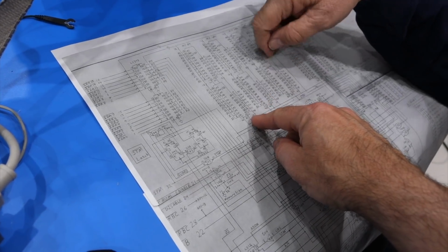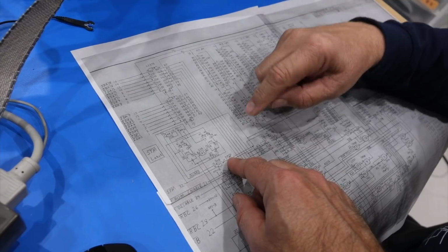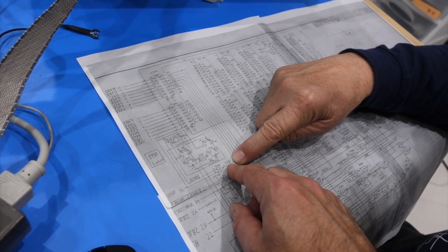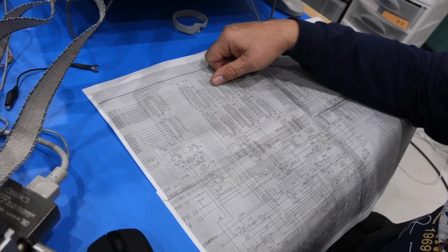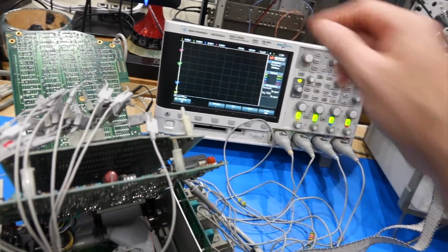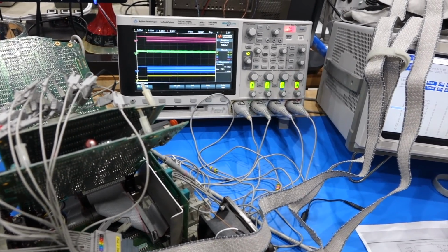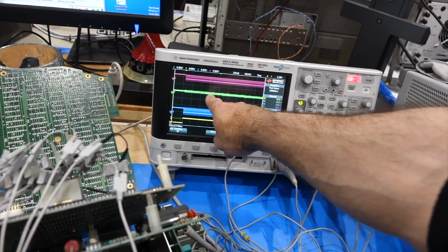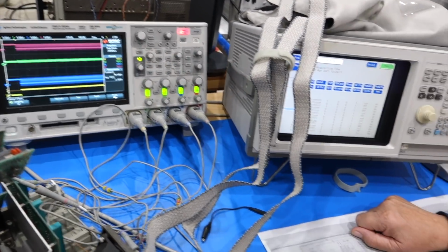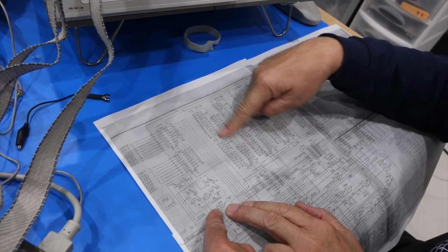So we're looking at one of the enables, which is STM prime, and STM prime should be mostly driven by STM, so that's start memory. And so I have STM on red and STM prime on green, and it's just one inverter gate, and we definitely see the memory access, but we don't see STM prime. And STM prime is latching everything, so it wouldn't latch our address. That would explain it. Nor select the output.